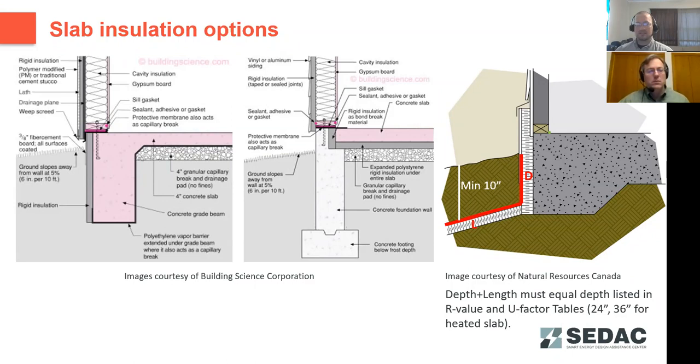There are a couple different ways that can be done. You can do, for the monolithic slab examples we show here, all that insulation can go to the exterior. For a floating slab on a footer, you could have that insulation wrap around the inside slab. I know we've run across some details, especially with heavy traffic, where you're having trucks or dollies rolling across that insulation that kind of creates a weak point for the edge of that slab. There are exceptions that allow structural components there that aren't necessarily insulating materials, but there are some requirements there for a thermal break, just to maximize the separation from the inside slab and the exterior of the building.